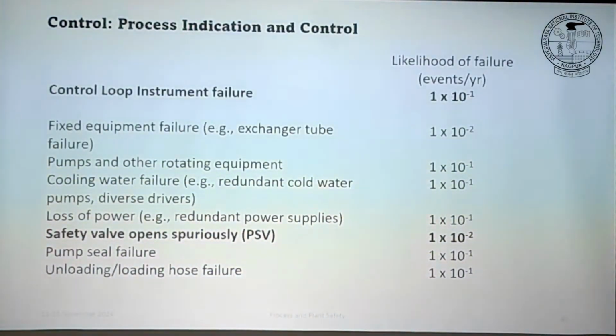What we were saying earlier, that you need this pressure sensor to do its job when it is required, but it can fail. So it's actually the probability of this sensor working on demand. And demand is not 24 hours a day, 7 days a week. It comes sometimes, because pressure is increasing only once in a while.